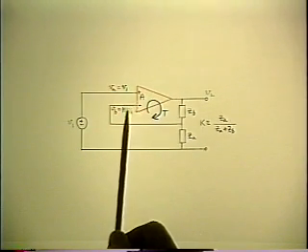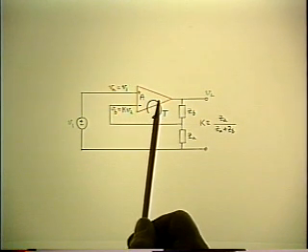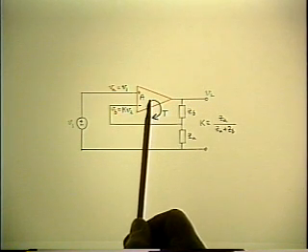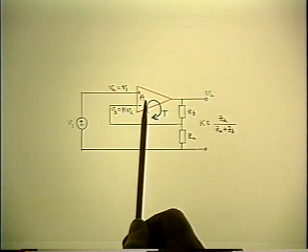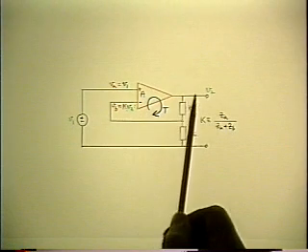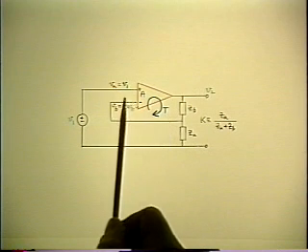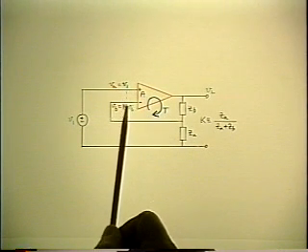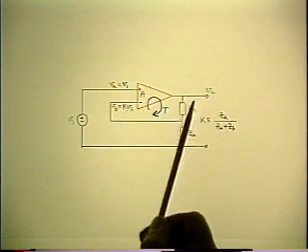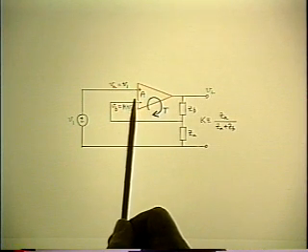Well, the usual thing that happens is you make the assumption that the A box is infinitely large gain, which is a pretty good approximation, isn't it? And the reason you do that is that whatever the output voltage is within its dynamic range, if the gain A is large enough, the error signal or the differential signal at the front end becomes vanishingly small. Whatever the output is, it takes a vanishingly small input to get it, the larger gain you have in the forward path.